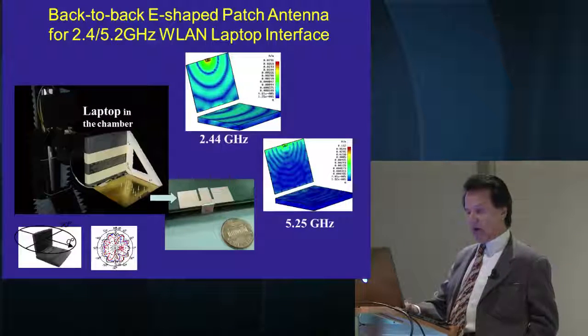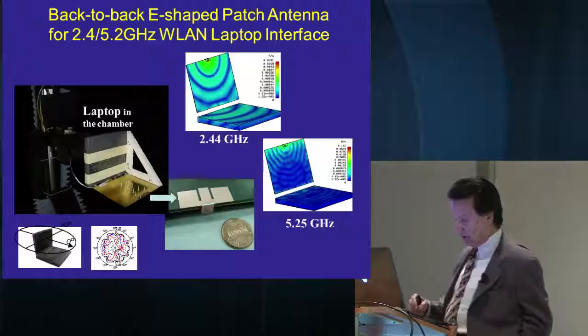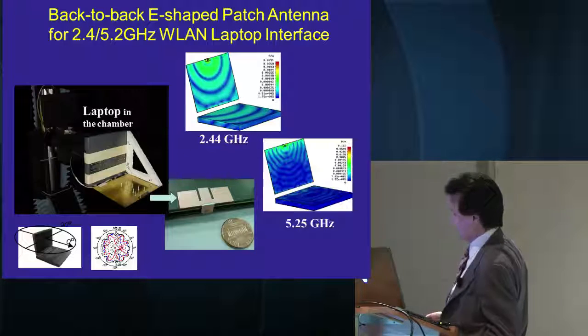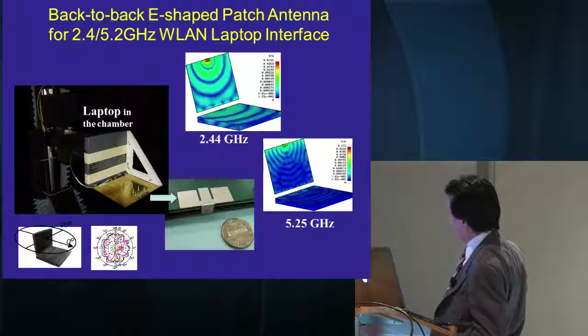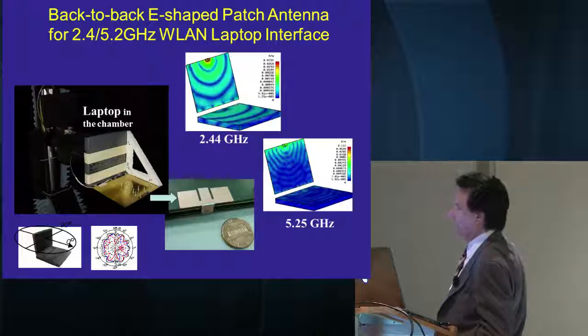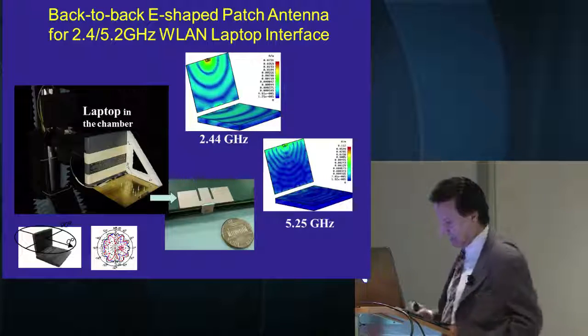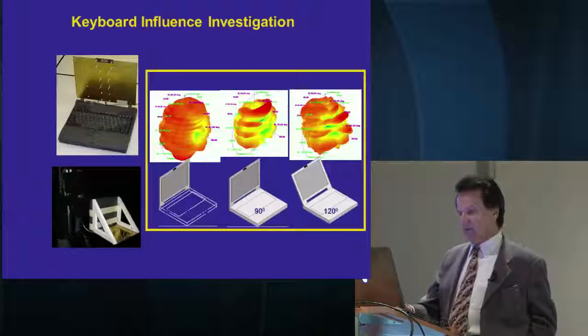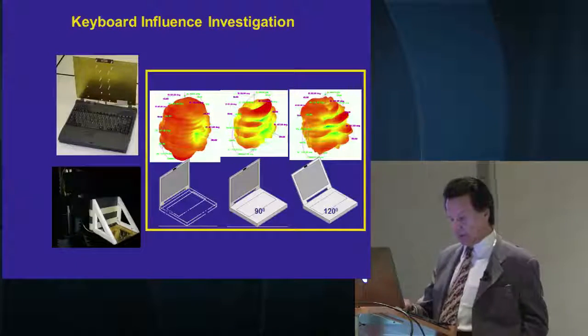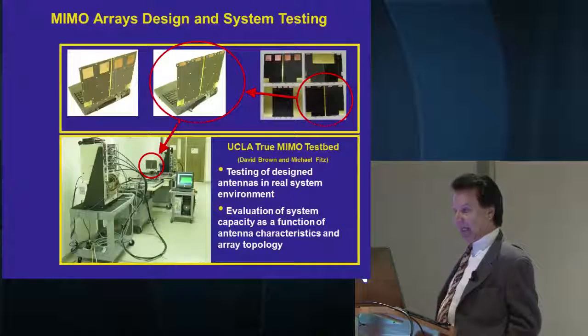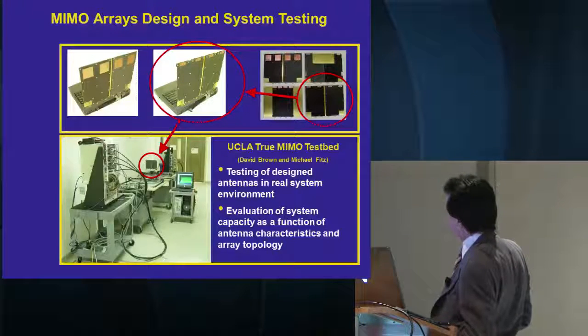Now, we also did some actual deployment in our anechoic chamber at UCLA to do some measurements. So this is your laptop, and this is the screen. This is a representative screen with some antenna mounted at the edge. Then we did the measurement. These are actual measured results, and they correspond very well with our simulation. And then we evolved that to some MIMO deployments.